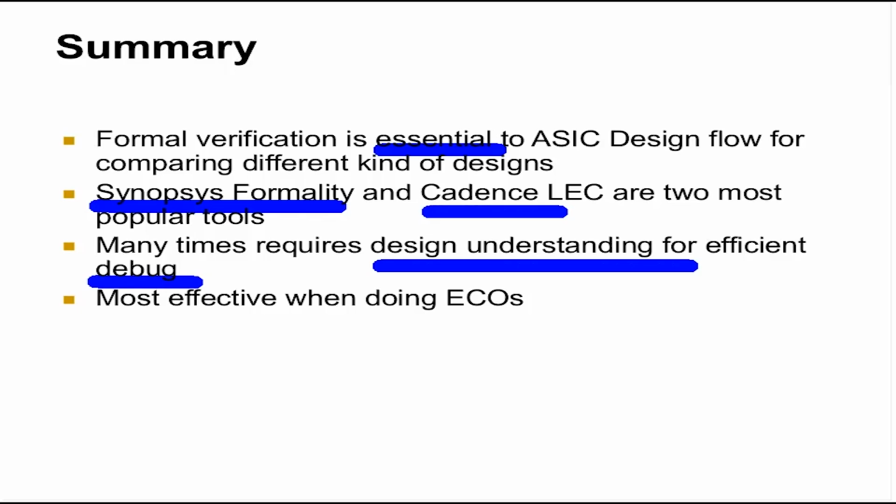Any logic equivalence tool in your flow, you can have one, either Cadence LEC or Synopsys Formality. But it is essential. It is most effective while doing ECOs. What are ECOs? Now let's say you have done synthesis. A decent size, a big design will take about a day for synthesis, a few days more to make sure all the synthesis reports are correct. It will go through the post layout backend flow, which will take multiple days. It will take 4, 5, 6, 7 days to get the routing completed, and then the backend engineer plus the front end engineer both will start fixing the timing using some tool or flow, and in some more days they will be very close to sign off.